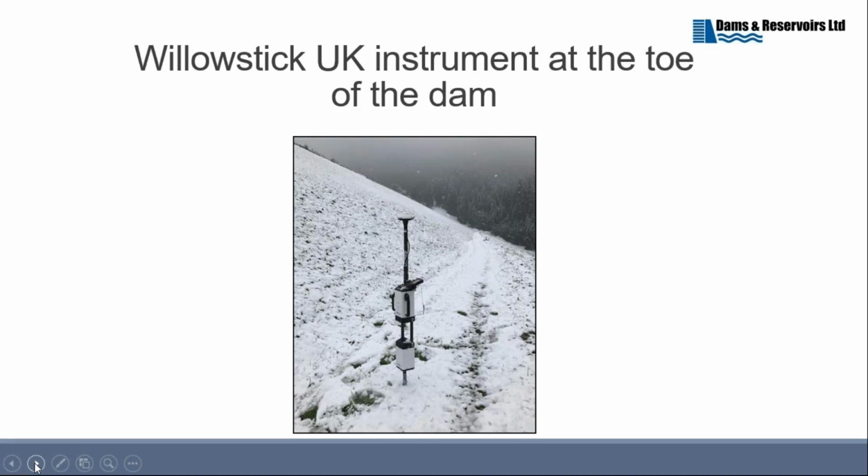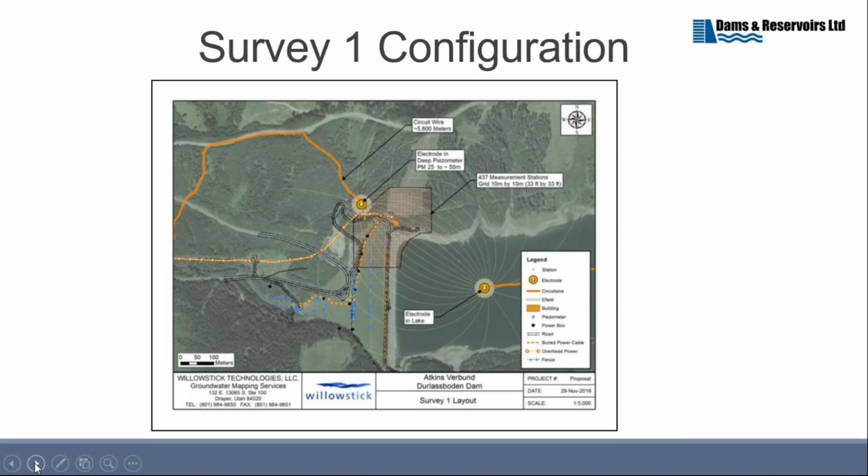But we went out with an open mind as always, thinking, well, is the leakage through the dam? Is it through that silt layer? Is it in the bottom of the valley? Is it around the side? Where is that leakage? Not very hospitable conditions, but beautiful work. There's the instrument sitting out on the dam, and that's the instrument the guys would walk over the full face of the embankment and the abutments and the area outside it, taking instrument readings at about 5-meter intervals.